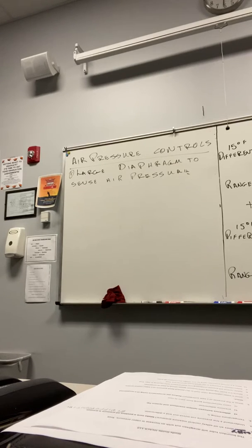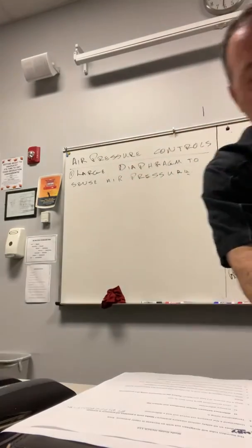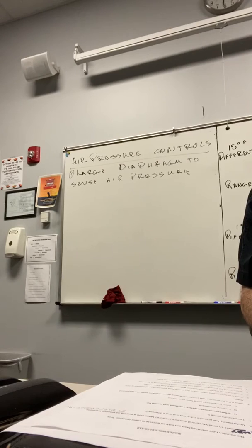This control safety switch should be treated as such. It has a very light sensitive sail and will let you know if the air is on before the electric strip heaters come on because they can burn up. Air switches or sail switches are used to prove combustion air before turning on a gas valve.